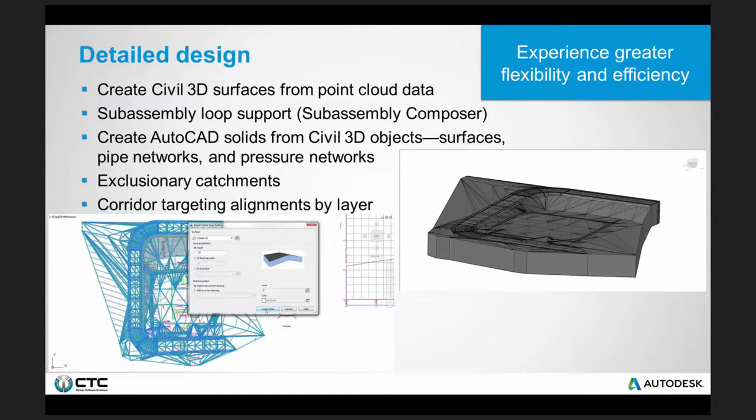You want to print a surface of a site, for example. It's hard to print a surface. We need to go down to some kind of datum. Well, you can display that and show that in Civil 3D, but you can't really get that into some usable format. Well, AutoCAD solids are very usable for 3D printing. So we can extract a solid from our surface and tell it to go down 10 feet or to go down to a datum elevation of 800, for example. So extracting information from Civil 3D objects into more universal forms of AutoCAD solids. So nice helpful option there.